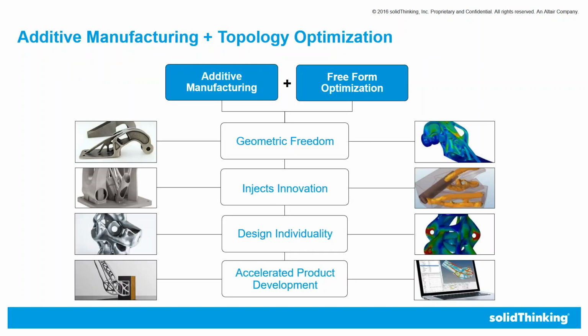Now, when it comes to additive manufacturing, by the way, let's step back one more time. Topology optimization has been used by industries, the aerospace industry or automotive, for a long time. Inspire comes up with the most organic shape for a component, how nature would design something, like imagine the bone. Bone won't be a straight line. That's the organic design of topology optimization, and that's exactly what Inspire does in the background. Then we can force Inspire to use some manufacturing constraints. But the organic design it comes up with is the best suited for 3D printing.